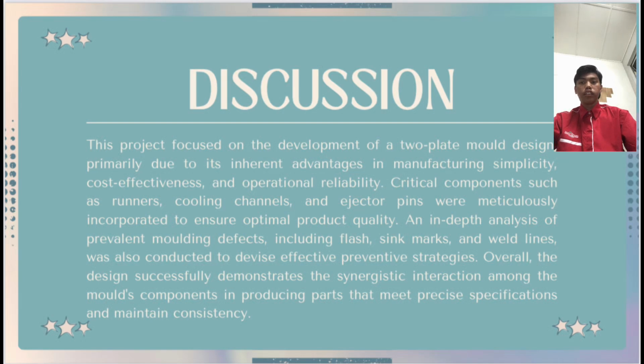An in-depth analysis of prevalent mold defects, including flash, sink mark, and weld line, was also conducted to devise effective preventive strategies. Overall, the design successfully demonstrates the synergistic interaction among the mold components in producing parts that meet precise specifications and maintain consistency.